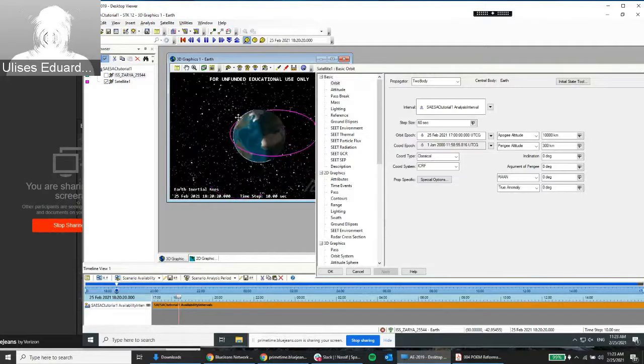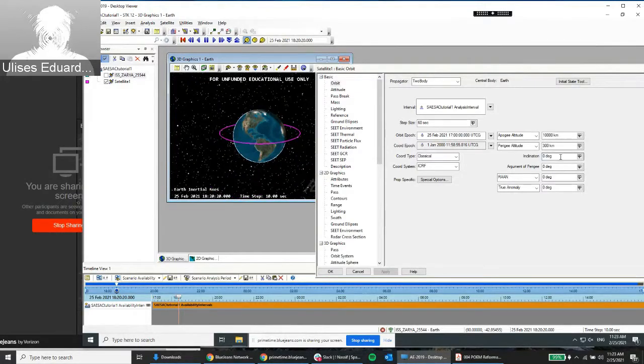Other than that, we have flexibility in a lot of other ways. For example, if we go back to 28.5 degrees for orbital inclination, and we say, okay, let's change the right ascension of the ascending node, which is the point in your orbit when we cross the equator, say that we make that 30 degrees. Now the orbit plane has shifted, and we can make that as little or as big as we want. And so, as you can see, that's pretty useful because we can essentially define arbitrary orbits at arbitrary times with arbitrary orbit propagators, and that's super general.